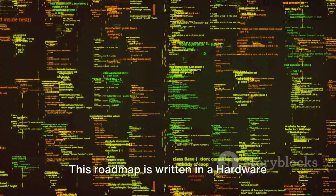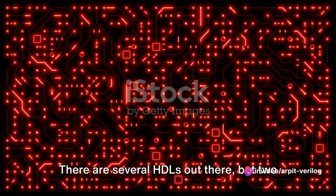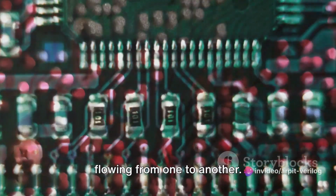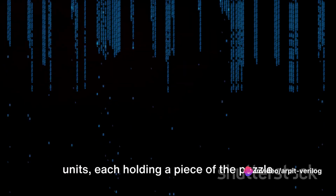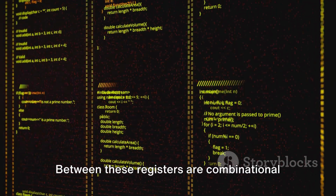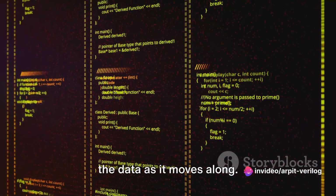This roadmap is written in a hardware description language, HDL for short. There are several HDLs out there, but two of the most popular are Verilog and VHDL. Now, you might be wondering, what does an RTL code look like? Well, it's a series of interconnected registers with data flowing from one to another. Think of these registers as tiny storage units, each holding a piece of the puzzle that makes up the overall functionality of the chip. Between these registers are combinational logic blocks, which perform operations on the data as it moves along.